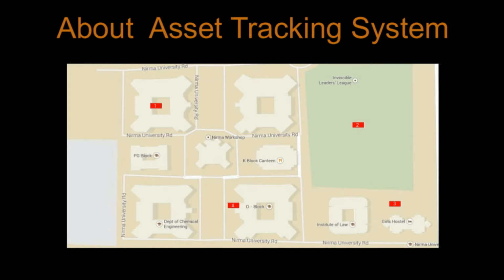Formerly, asset tracking was done by observing the presence of each asset, which obviously requires a large amount of time and manpower. This scenario can be changed by implementing an automatic asset tracking system. Our system is based on the RSSI measurement model. RSSI is received signal strength indication. It means the received power of the RF signal from the asset tag, which is used to estimate location. RF tags will be fixed on each asset which is to be tracked.